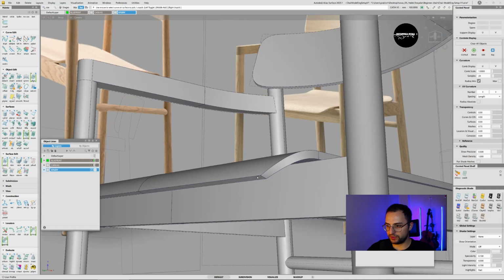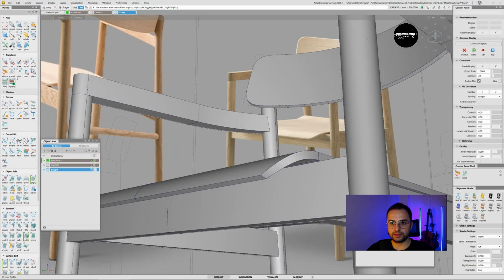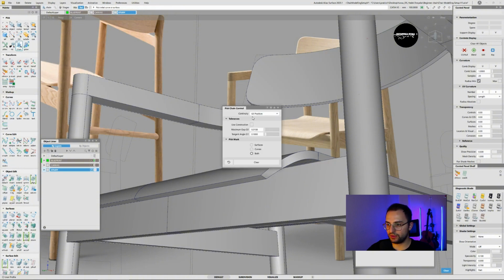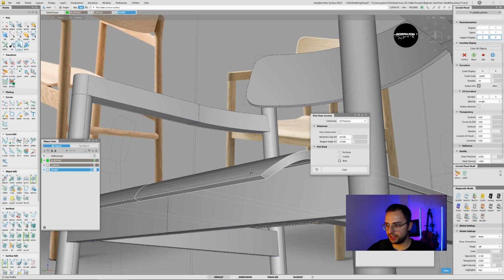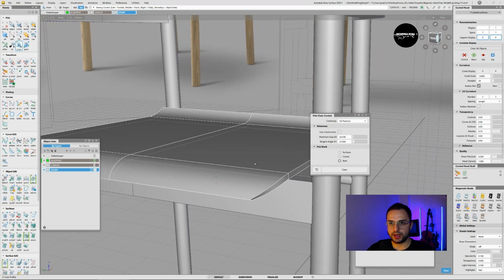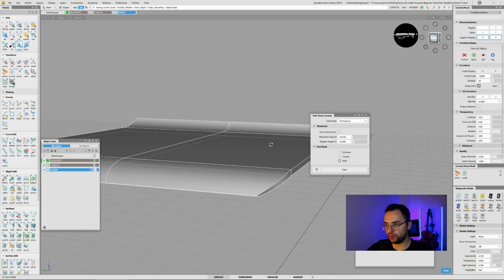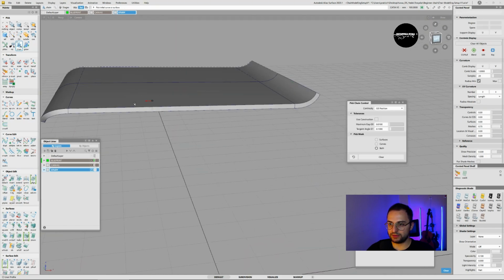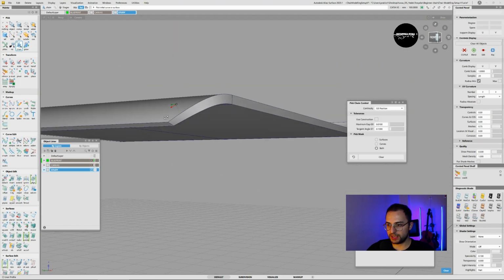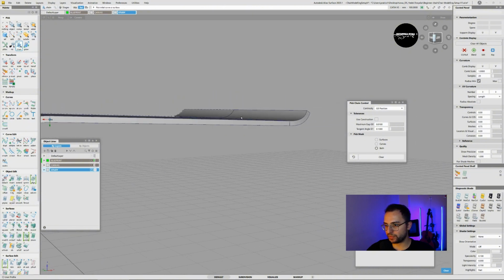Let me just first select the surfaces. Instead, select one by one. There is this chain tool here. Double click on it, activate as G0 and hit on one side. It selects the positional surfaces, and you can go on, hide and select it, and you have the whole body. Okay, so we need the transitional fillets first at this edge and at this corner.